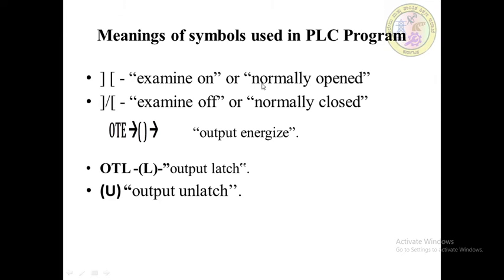Likewise, different kinds of symbols are used, so we need to understand some instructions. This open bracket instruction is called examine on, or normally open.